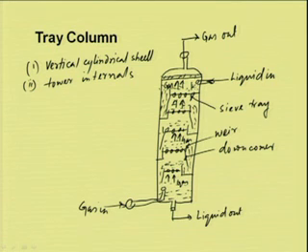and there are nozzles through which the liquid and gas are fed to the tower. In each tray the gas and the liquid are finely dispersed, and then the gas disengages and flows to the upper tray, and the liquid flows through the downcomer and comes to the tray lower down.